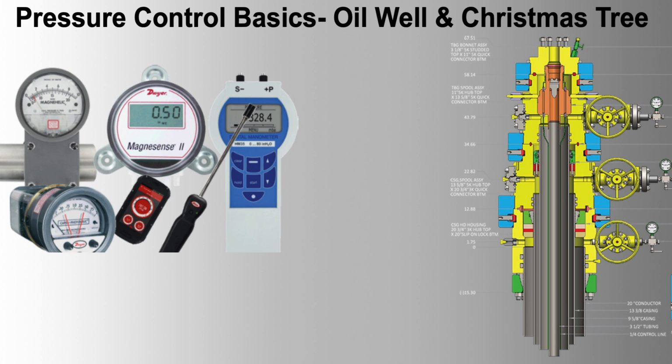Example 2. Downhole pressure gauge. Design. Quartz pressure gauges are known for their high accuracy and stability, making them suitable for downhole applications. Hastelloy C276 is selected for its excellent resistance to corrosion in high temperature and high pressure environments. Selection. The gauge's accuracy of 0.01% allows for detailed pressure profiling and reservoir analysis. Its integration into the downhole tool string enables continuous monitoring during drilling and production.